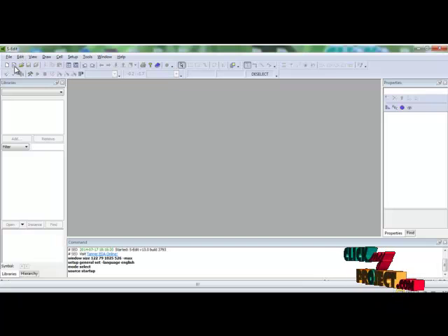By clicking this, we can start a new project. To start every new project, we have to open a new cell. By clicking the cell, we can design a new circuit. In the cell, we can include a lot of libraries which consist of transistors, CMOS transistors, resistors, capacitors, such as general devices. After designing, we have to set up the simulation. After that, we have to save the file and execute it. If we execute the circuit in the correct manner, we can get the output in W-Edit.